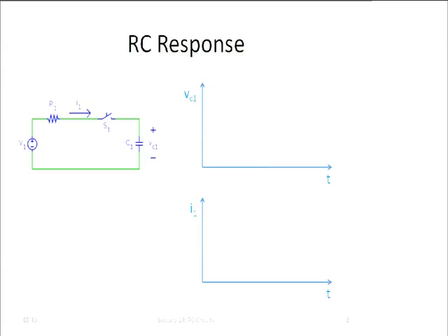So the capacitor gets charged, and then, of course, the voltage initially is what? Yeah, 0. Initially 0. Why? Well, because I told you that the capacitor was initially discharged. So we start out here at time equals 0. This is a little bit of a contrived example, of course, much like many of those in the book. We start at 0, and then the capacitor gets charged. So if we wait for a very, very long time, where does the voltage go? What does the voltage reach ultimately? V1, right? It does not go to infinity or something like that.